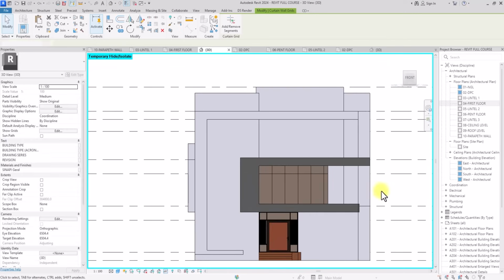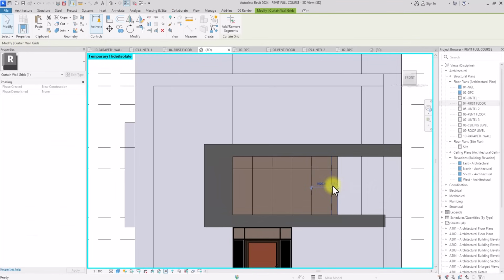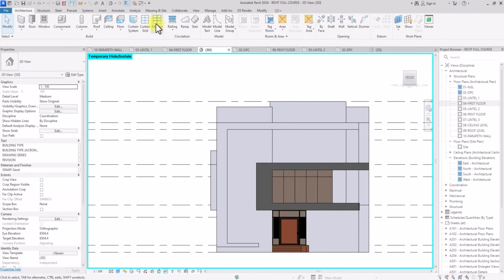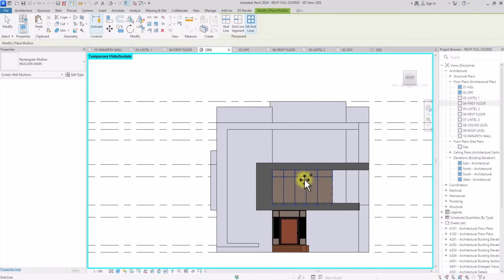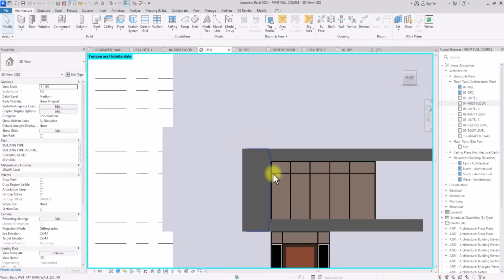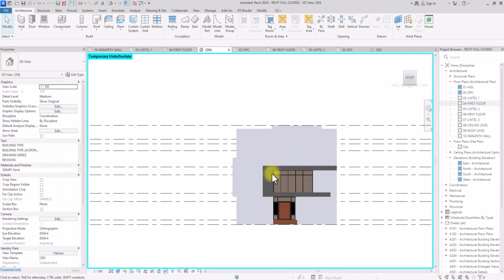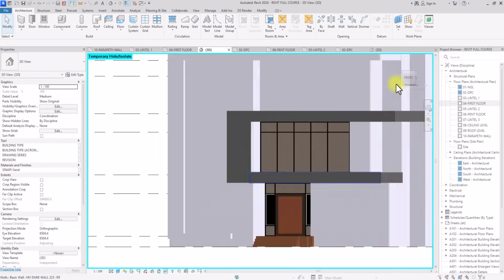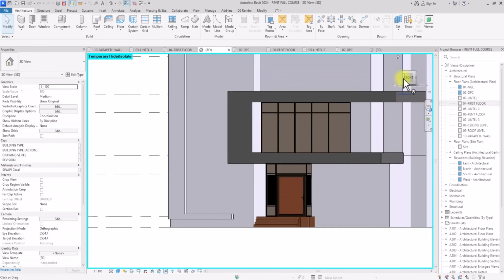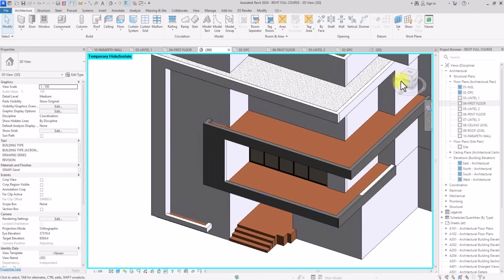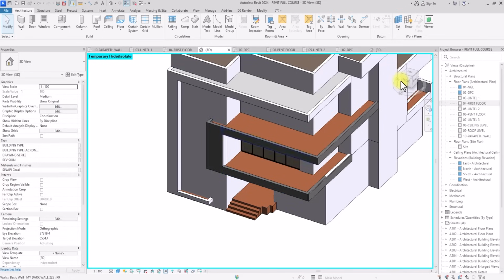Okay, I actually don't need this cutting grid here, so I'm just going to go to mullions and go to all grid. So now I've done this, I'm just going to click on tab because I want to put a door inside this curtain wall. Since I don't want to start going to the other project, I'm just going to import this door.